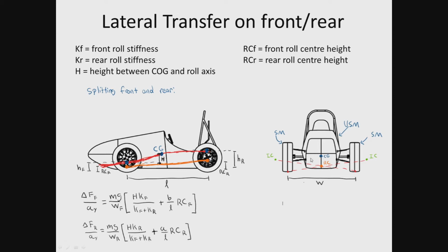Knowing this, we can define the height of the roll center at the front and the height of the roll center at the rear, and then an axis between the two of them, which we refer to as our roll axis. You should note that as your suspension moves, these instantaneous centers will move as well, and the roll center will then migrate. So this is not a constant position. This axis will shift as the vehicle moves around. We are only considering right now the nominal position. So when the vehicle is at its static resting height, if you consider it as a non-moving surface, then we can define our roll center in one place, but this migrates as the car moves around. For simplicity of calculation, we'll consider it as if it acted on only one point right now.